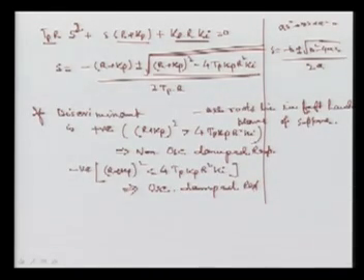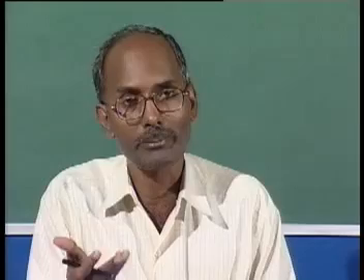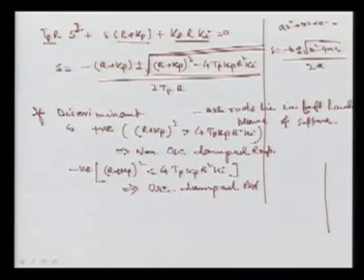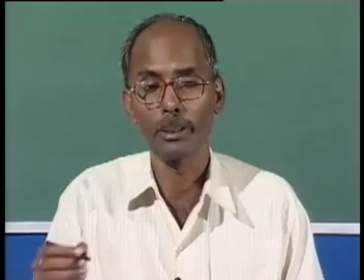If this is less than this, we get a negative sign here, and the square root of a negative is an imaginary term, so we get imaginary roots. Here is the S plane. In the first case, if it is positive, we get all the roots on the real axis. This is the imaginary axis, and here is the real axis. So all the roots are on the real axis, which gives non-oscillatory, meaning it will not oscillate, and damped, meaning damping will be achieved.